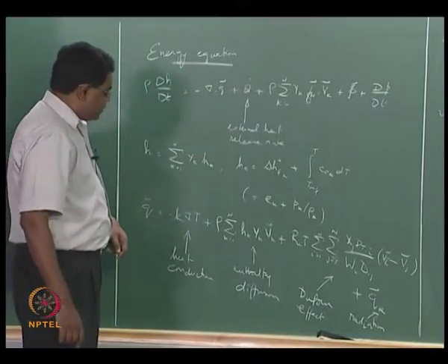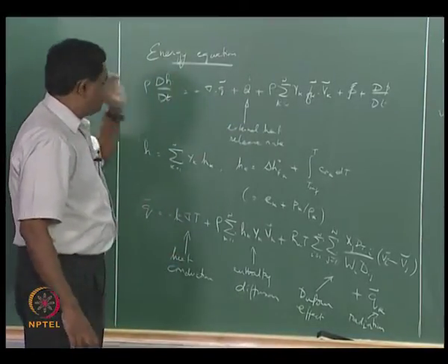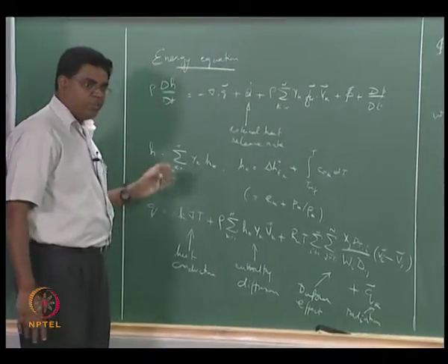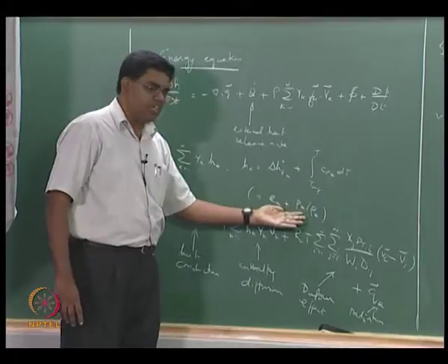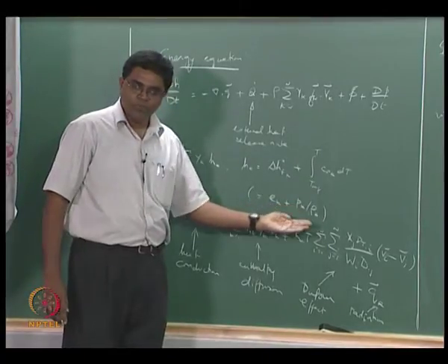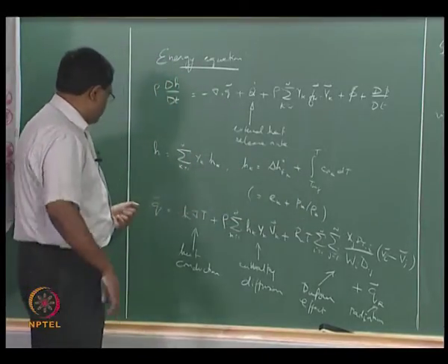Of course, if you want to rewrite this equation in terms of internal energy instead of enthalpy, you could derive this from noting that you can write this as Ek plus Pk divided by rho k for this Hk, and proceed from there.